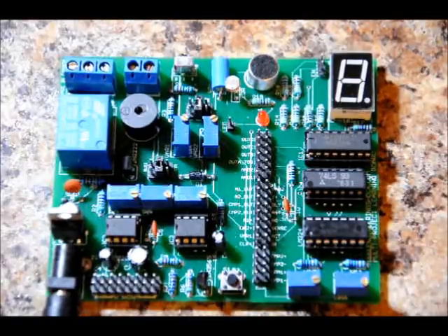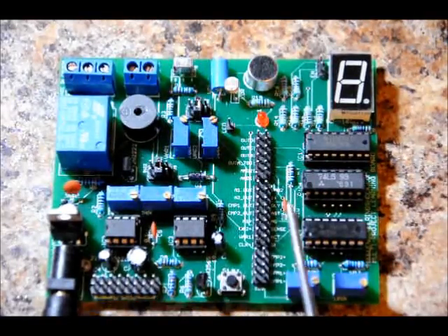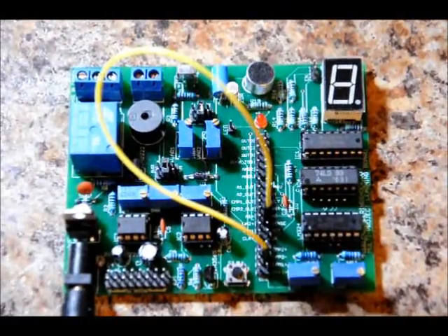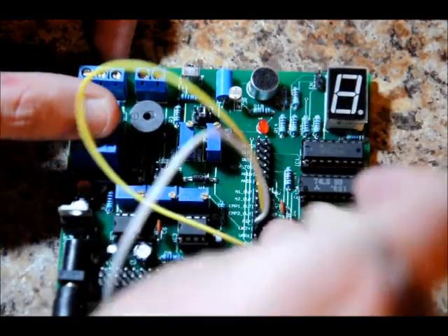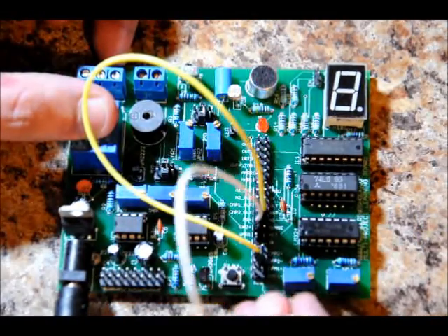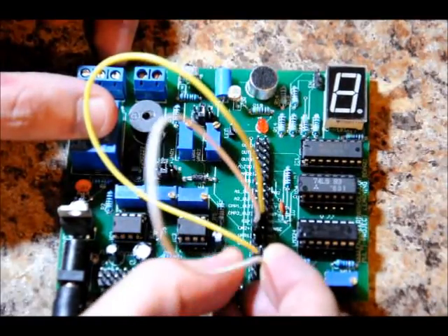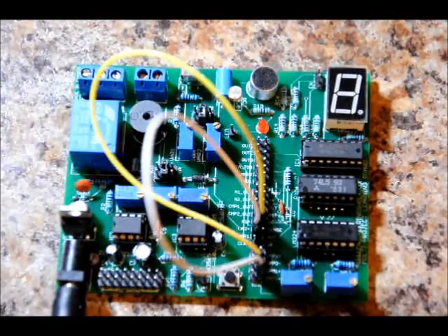So now what we want to do is connect our sense line, which is our LDR circuit, to the positive input of our first comparator. Now our comparator lines are at the bottom here. We want to connect our sense line to our CMP1 positive line. From there, we want to take our calibrated variable resistor output of 2.5 volts, VAR1, and connect it to CMP1 negative, our negative comparator input. There are two comparators on the board, hence the CMP1 and CMP2.